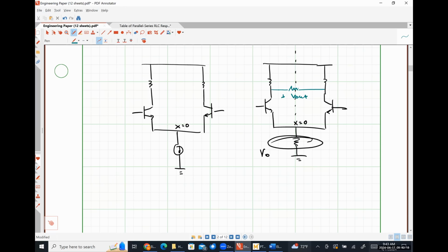Yes, real quick on that. If we're allowed to assume just a one-sided answer, do all of that? 100%. You can do a formal derivation like we did in class. You can analyze the left-hand side and the right-hand side, where we apply 1/2 of the differential input voltage on one side and negative 1/2 of the differential input voltage on the other.